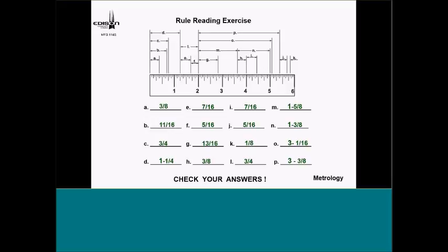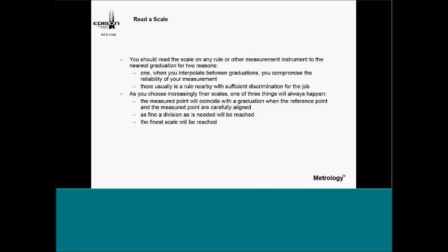Just to let you know, in my tolerances, my scale dimensions are plus or minus 1/64th, and my precision measuring instruments are plus or minus 0.001 inch. And then later on, we'll talk about degrees, but I allow plus or minus 15 minutes. It's interesting, because sometimes I'll get students that have never done much measurement at all using a 6-inch rule. Okay, so how do I read it?